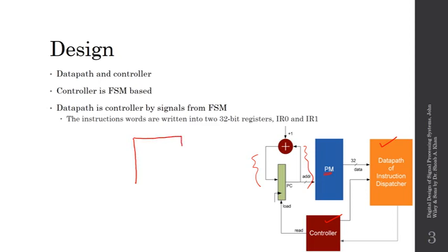When we say that our system or our program memory can hold two types of instructions, a short instruction of 16 bits and a long instruction of 32 bits, what does it mean for the contents of the program memory? Now we can assume a few instructions. We can say that in the first location we have a long instruction. That means a 32-bit wide instruction is already placed in location number 0. Location number 1 can hold two short instructions.